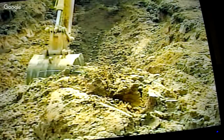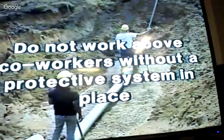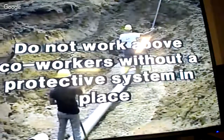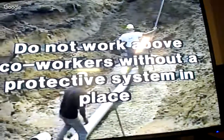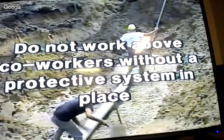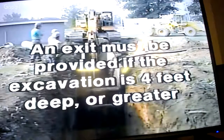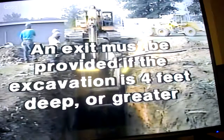When working in a sloped or benched trench, some practices should be followed. You should never work on the face of a slope or bench above another coworker. This is only allowed after a protective system has been put in place to prevent materials from falling into the trench. If the excavation is 4 feet deep or more, an exit must be provided.